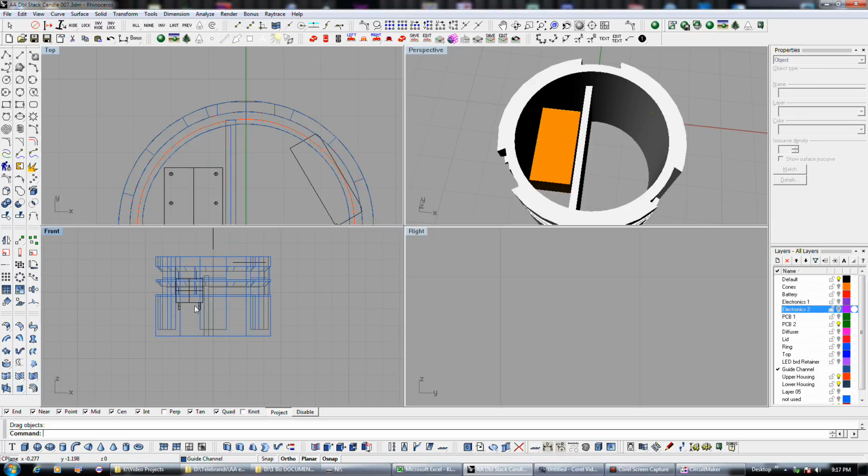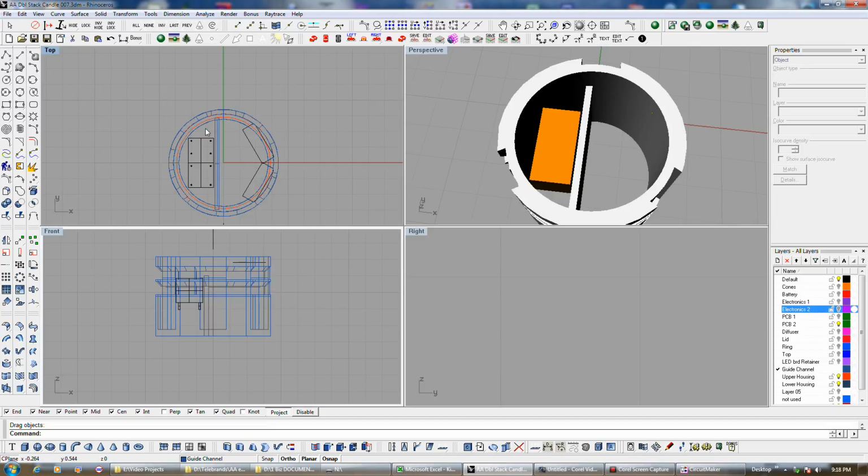So, to provide us some clearance, there's still quite a bit of room to stuff wire, both underneath this and so forth. There'll have to be a little bit of excess, because when the things are split in half, it's pretty hard soldering stuff. You've got to bend them at a 90-degree angle to each other to keep the lead wires short, but at the same time long enough to where you can solder things together. So you can't put an excessive amount of wire slack in, but you can put enough.